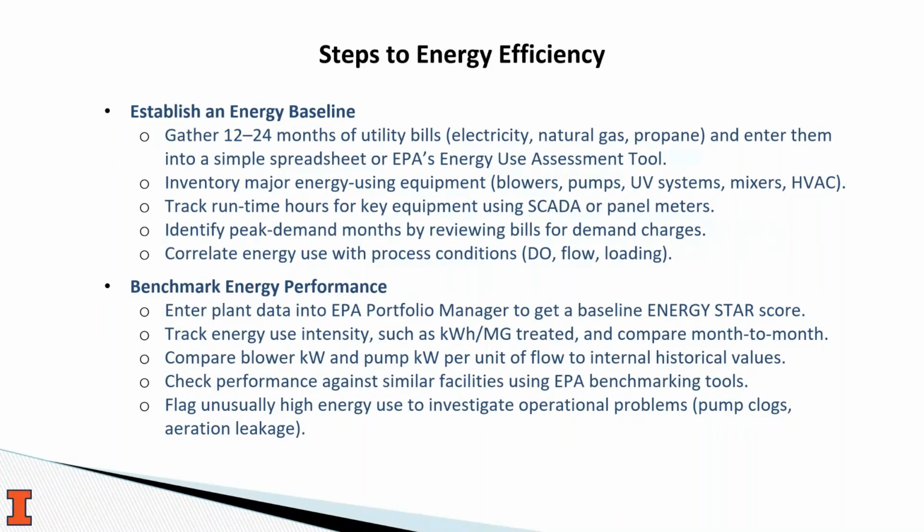It's also helpful to link this data with process conditions like flow or DO, dissolved oxygen, since this can help you determine if high energy use is because of an equipment issue or if an operational change might be required to optimize your process. Once your baseline is set, the next step is again benchmarking.